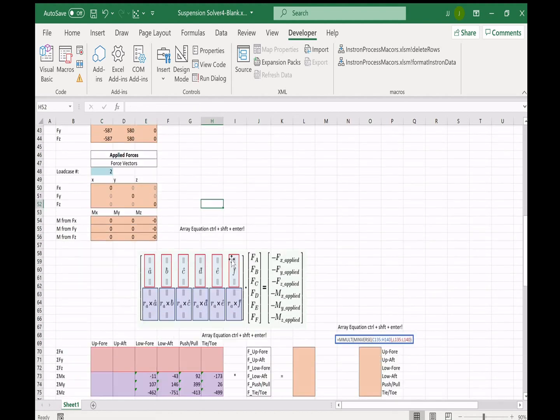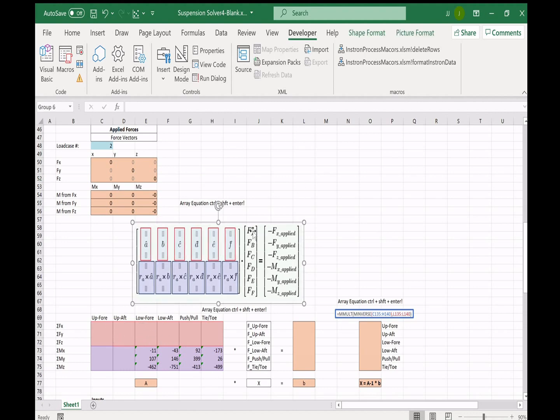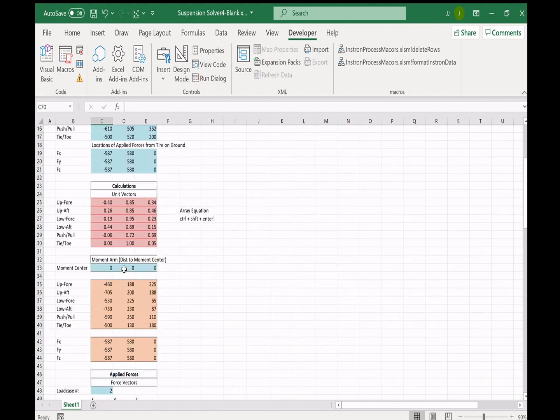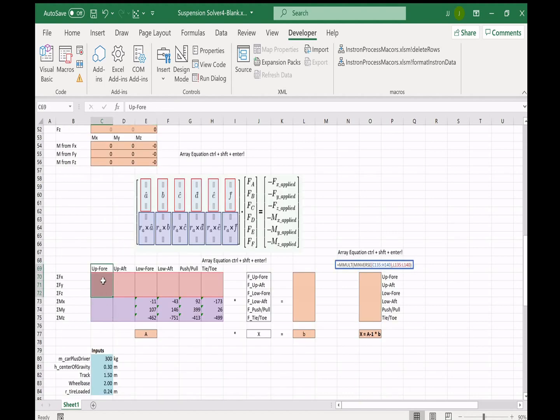Perfect. So now we need to throw everything into our large matrix here. I've copied in our MathCAD image here. So I just want to remind you how in the first column, the top three here are the unit vector A, whereas before these are organized horizontally, we need them vertically here. So all we're going to do is transpose that. And then this is our unit vector for B, unit vector for C, unit vector for D, and then we have our alternative names here.